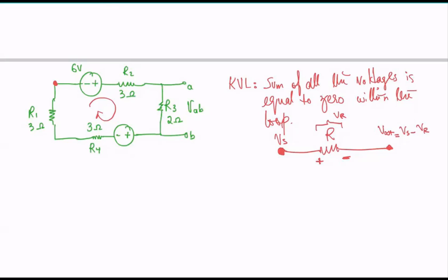So when you are moving clockwise, I'm going to pick up this starting point right here. So clockwise would mean I'm going to go this way, okay? And then go this way, and then go this way, okay? I see the polarity of the power source is such that I'm going from negative terminal to positive. So we would consider it as a boost, okay? So think of it as you are climbing up the hill, from negative to a positive position, okay? And if you're going to give it some magnitude, this is 6 over here, correct?